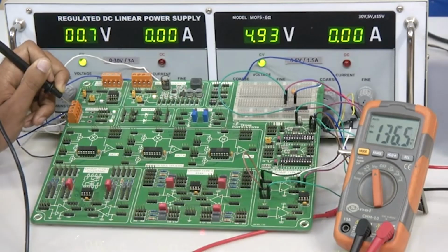See this. So we got 136, 137, it is doubling, because we are adding one weight per bit. Now from the 2 raised to 2 bit we have gone to the 2 raised to 3 bit. So we are adding one more 2. So it has become 137 millivolt, but you can very clearly see the digital to analog conversion happening. From a low voltage of 31 millivolt, 26 millivolt with 1 bit high, we have reached 137 millivolt.